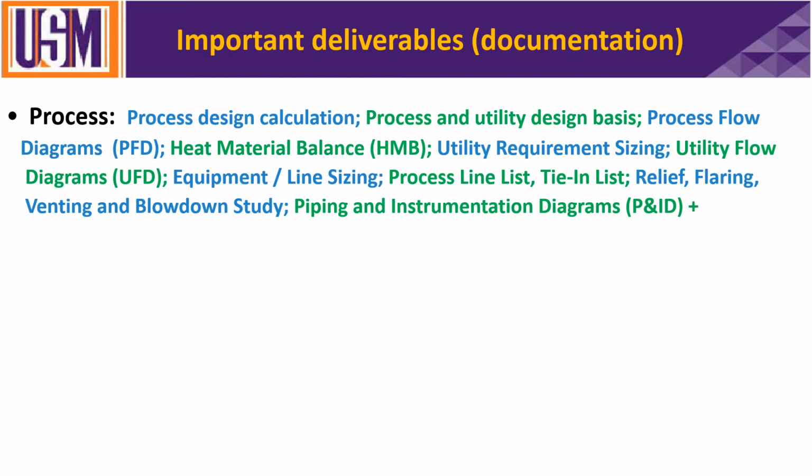Other documents include the piping and instrumentation diagram. This is the most important, the P and ID. This is more detailed than the UFD. P and ID is a detailed diagram with the material, with the thicknesses, with properties. So you'll have the UFD, the normal design flowchart, but at the bottom you'll have numbers, number 1, number 2, number 3. In each one everything will be defined, including material, temperature, pressures, everything you have to define in this P and ID. But control is usually not included.